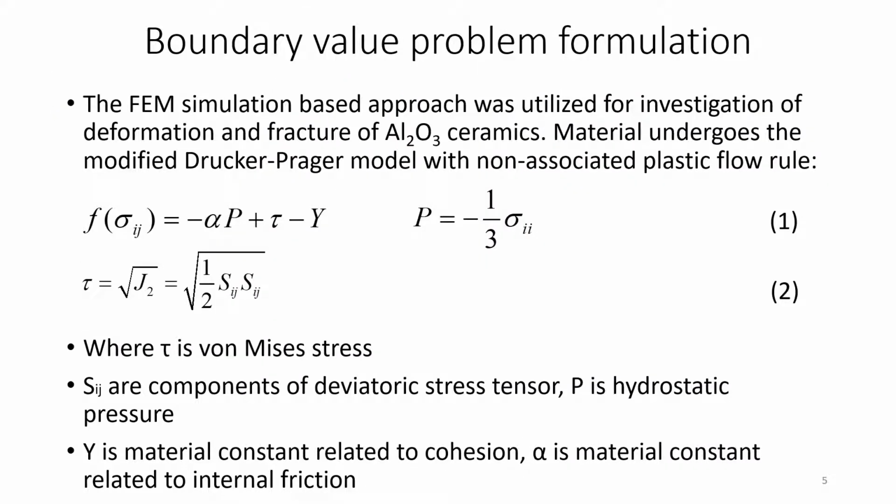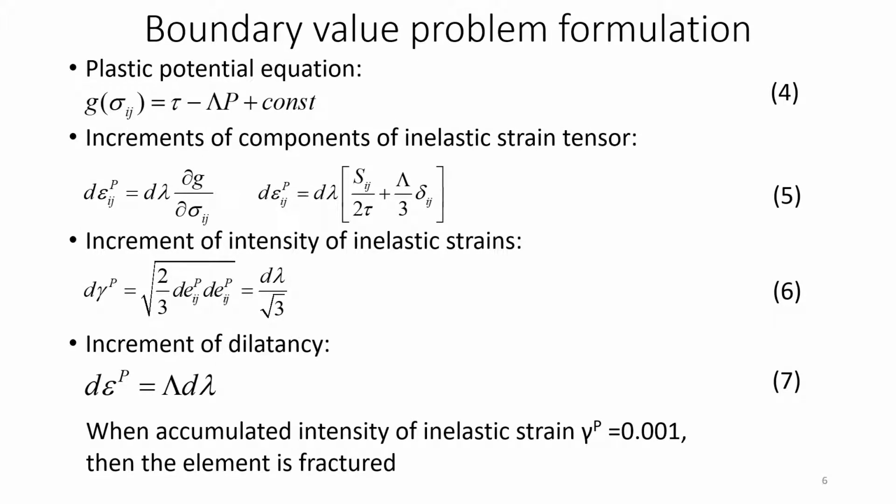In order to simulate the deformation and fracture process of the material under consideration, we utilize the modified Drucker-Prager criterion with non-associated flow rule. Usage of non-associated flow rule is dictated by the more accurate description of dilatant behavior of material.